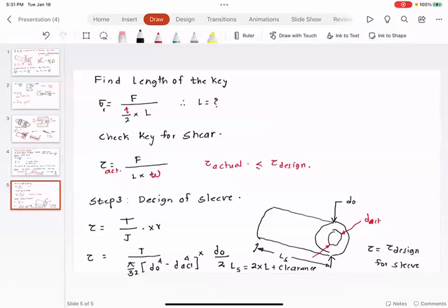Second thing you can do is, once you have gotten the inner diameter, once you have gotten the outer diameter, once you know the length of your key, you will go to a catalog. Like for example, you go to McMaster.com, or you would go to eBay, or Amazon, or Grainger. So these are the vendors of mechanical components, and you will get the stock item. You don't manufacture, because if you decide to manufacture it, it would be super expensive.